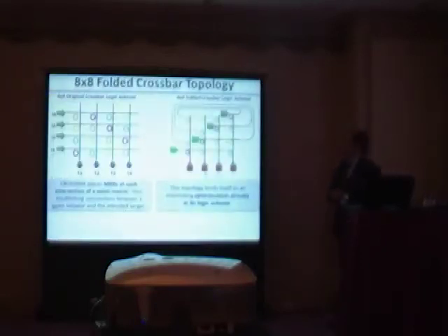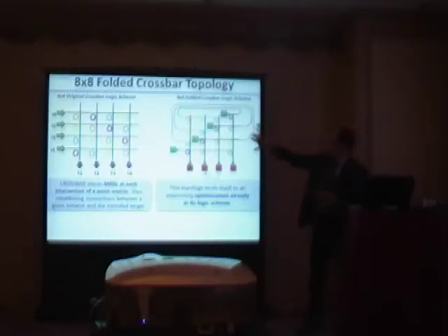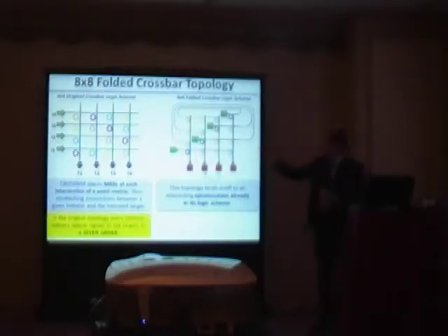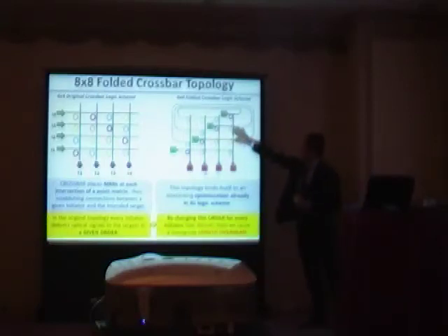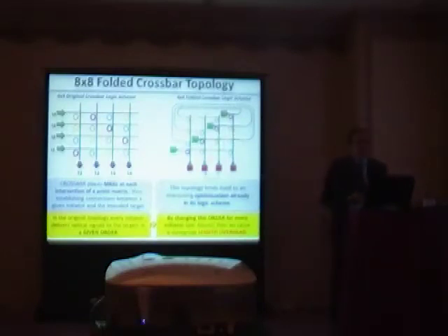Moreover, another topology analyzed was the unoptimized crossbar, which here we refer to as the 8x8 folded crossbar. For reasons of brevity, we explain its functionality by considering just 4 initiators and 4 targets. So if you look at the 4x4 original crossbar, notice that micro-resonators are placed at every intersection. And also, a specific initiator sends an optical message to all targets using a given order. So if you change this order, like this, we obtain a 4x4 folded crossbar.